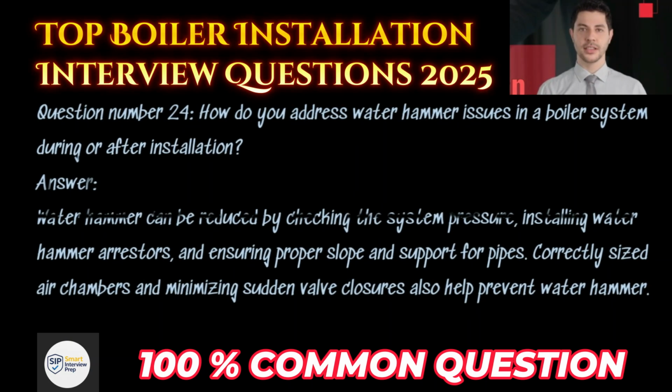Question number 24. How do you address water hammer issues in a boiler system during or after installation? Answer. Water hammer can be reduced by checking the system pressure, installing water hammer arresters, and ensuring proper slope and support for pipes. Correctly sized air chambers and minimizing sudden valve closures also help prevent water hammer.